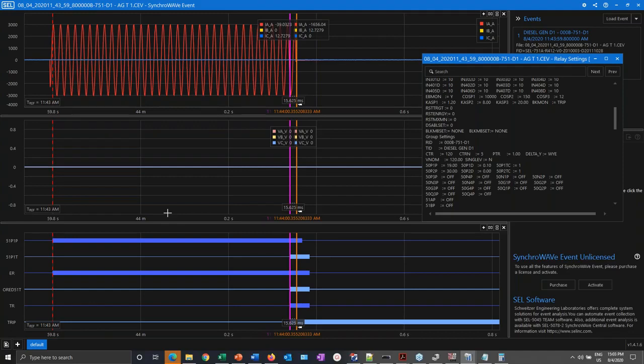So when you put all those little bits and pieces of time together, you get this difference. In my opinion, it's 4 milliseconds of processing, 8 milliseconds of the mechanical trip, and 4 milliseconds for the current to die out on the test set. That's my interpretation of this case right here.